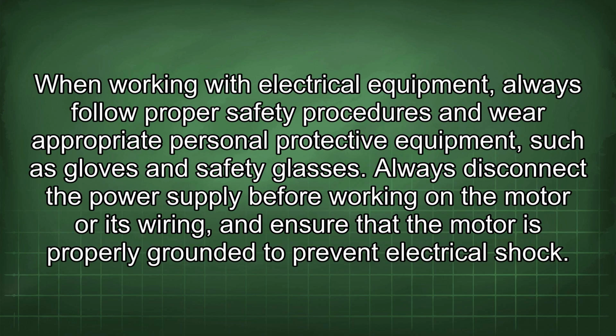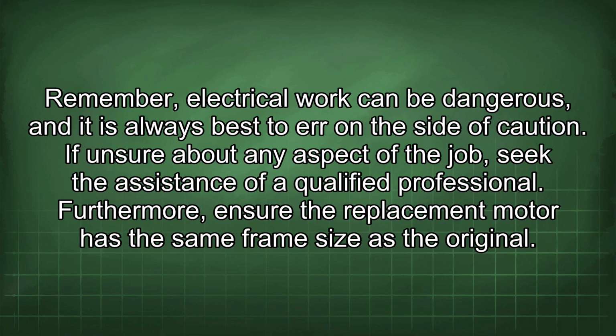When working with electrical equipment, always follow proper safety procedures and wear appropriate personal protective equipment, such as gloves and safety glasses. Always disconnect the power supply before working on the motor or its wiring, and ensure that the motor is properly grounded to prevent electrical shock. Remember, electrical work can be dangerous, and it is always best to err on the side of caution. If unsure about any aspect of the job, seek the assistance of a qualified professional.